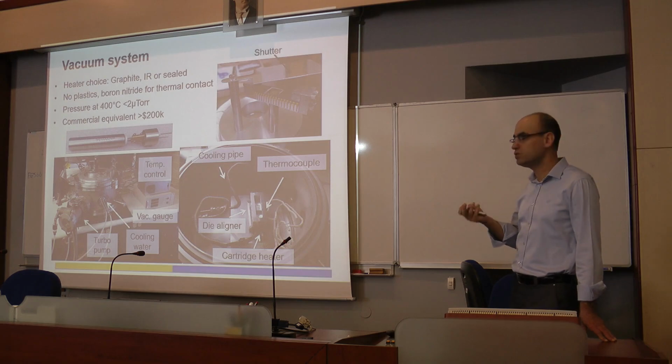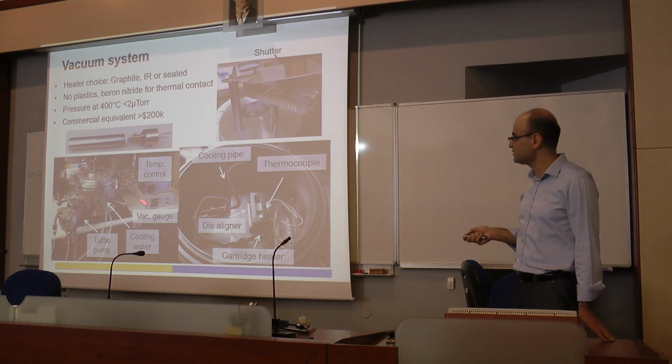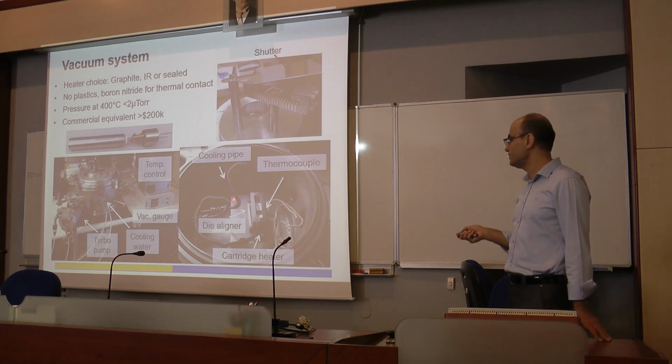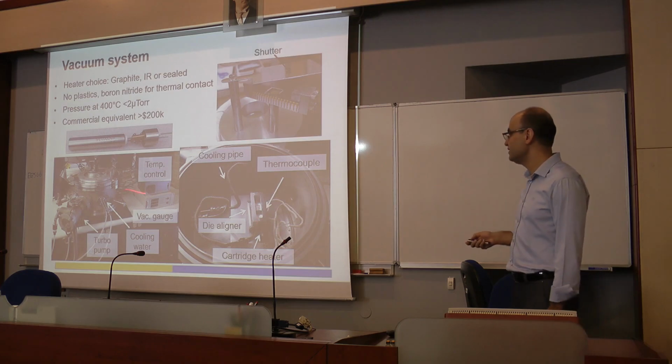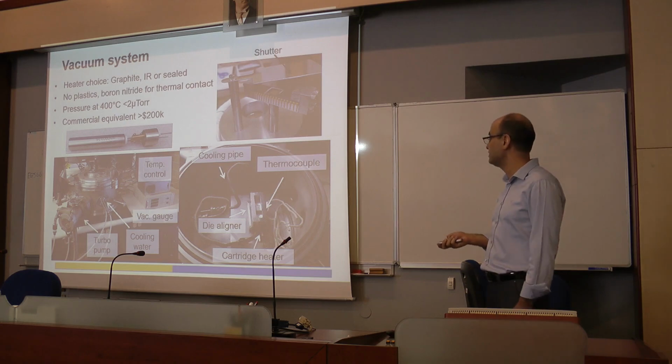I glue or I solder the lid to the package. This is not very simple. You have to have temperature control and vacuum control, and when this heats up in the vacuum, you need to cool it, and that's why we have water coming in and going out so that we can cool it in vacuum.